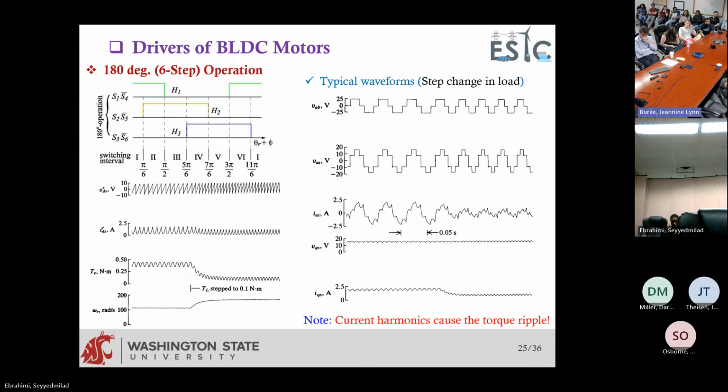This is the actual voltage of phase A. So you can say that this is a sinusoidal waveform, and the amplitude is 2 divided by pi multiplied by VDC, something like this, if I'm not wrong, plus some harmonics. Yeah, third harmonic. This is because of the logic of the switching. So that's one of the reasons.